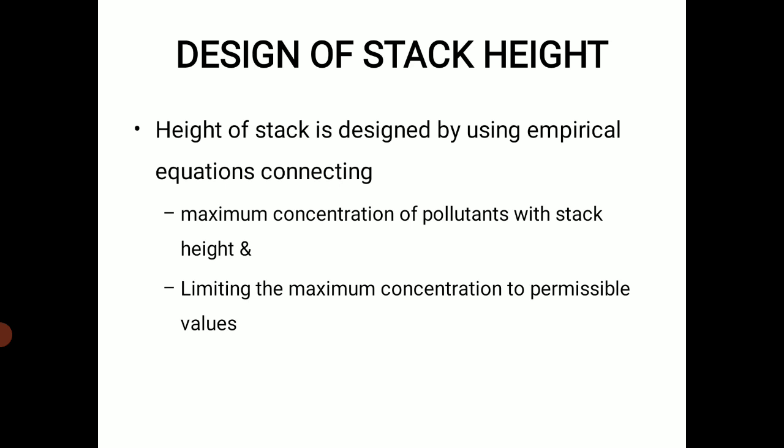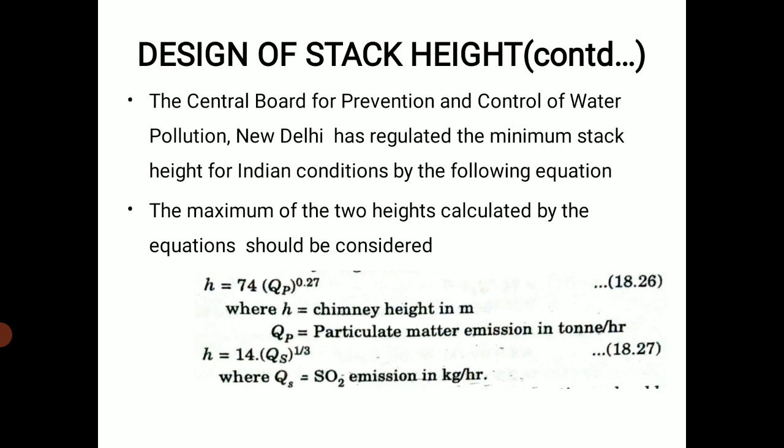Okay, so those empirical equations are based on maximum concentration of pollutants. The empirical equations are given by the Central Board for Prevention and Control of Water Pollution, New Delhi, and they have regulated the minimum stack height for Indian conditions based on these two equations. Out of these two equations, the maximum value has to be adopted.